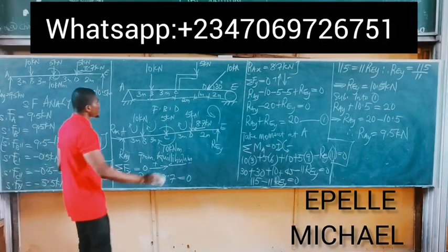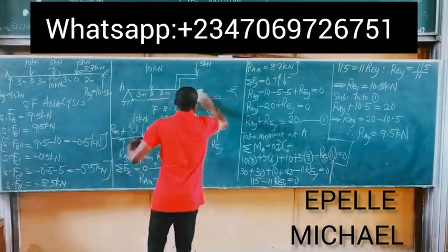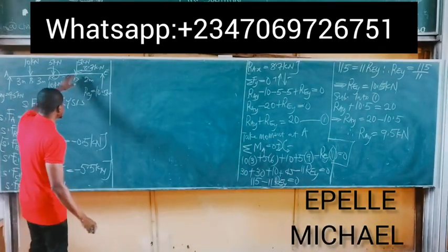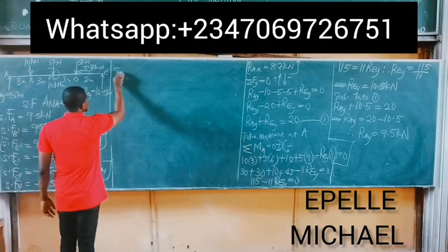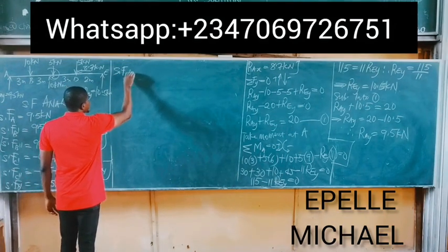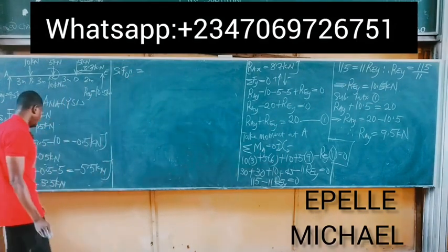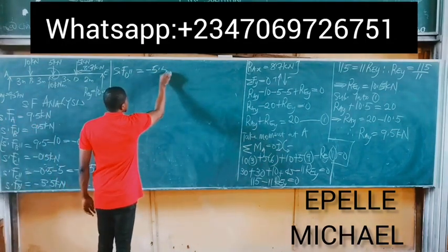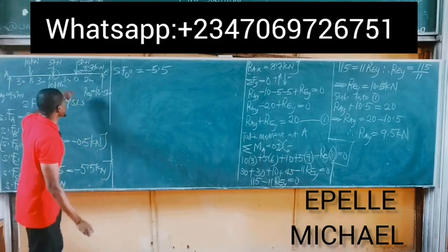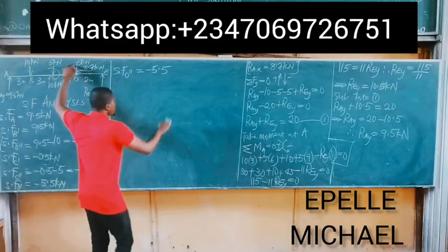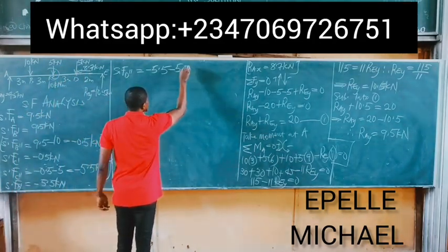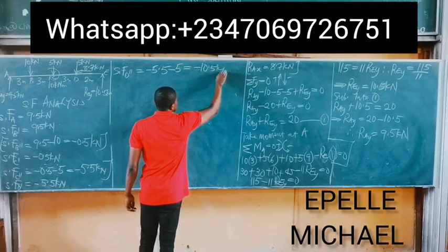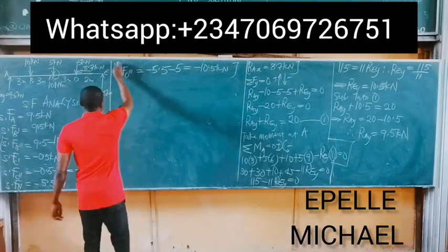Okay, so I can take this beam off now. So on getting to point D, we have shear force D prime prime, which means finally at point D, this same minus 5.5 kilonewtons force now encounters a downward force of 5 kilonewtons. So downward we simply have minus 5, and this gives us minus 10.5 kilonewtons. Okay, we'll keep this aside.